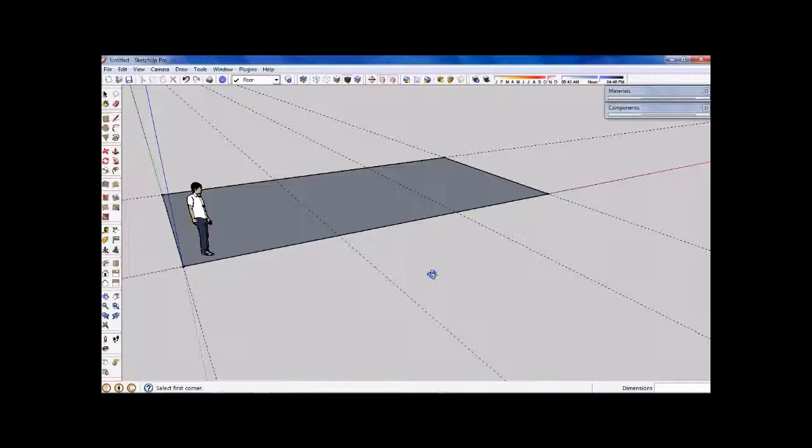The slab would actually be constructed from a 100 millimeter thick slab with a 50 millimeter sand bed underneath, and you add that up, it comes to 150 millimeters. Now I'm actually not going to model the floor to be 150 millimeters thick, because then when I look at the perimeter of the building from the outside, I then see the building floating above ground a little bit.